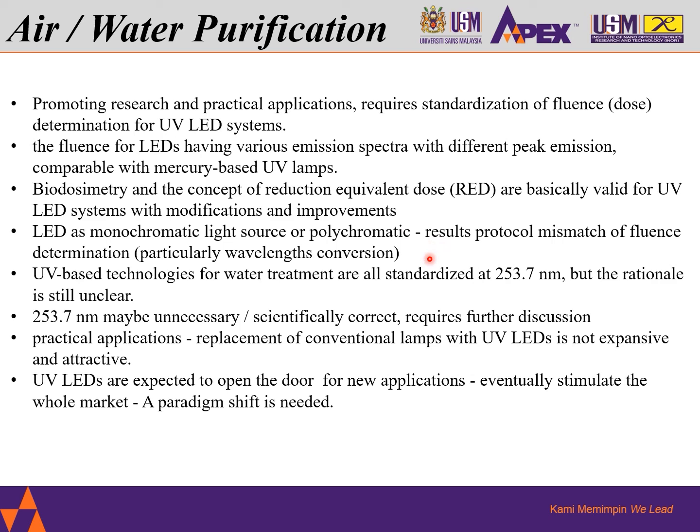Moreover, UV-based technologies for water treatment are standardized at the 253.7 nanometer wavelength, but the actual rationale for doing so for UV LED is still unclear. This kind of reference may not be needed or even scientifically correct for UV LEDs emitting outside of this particular wavelength. Further discussion is very much needed.